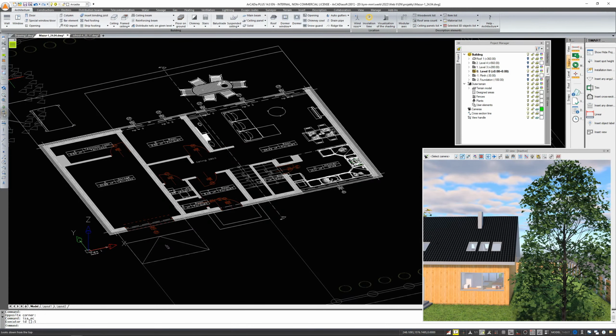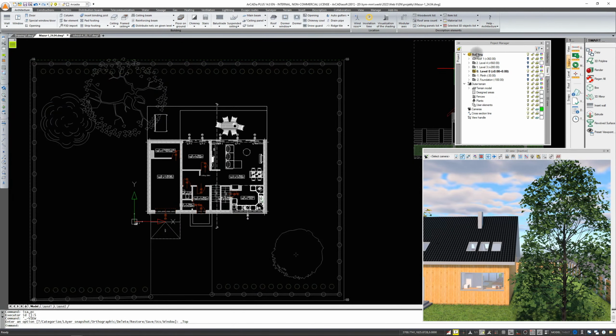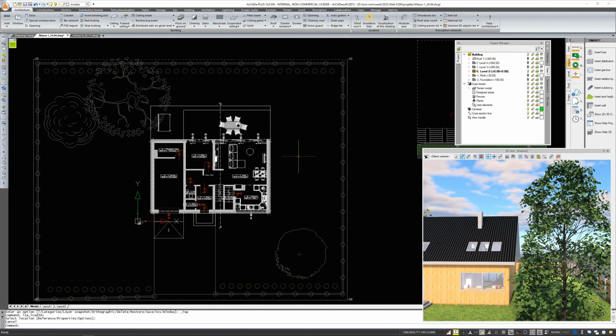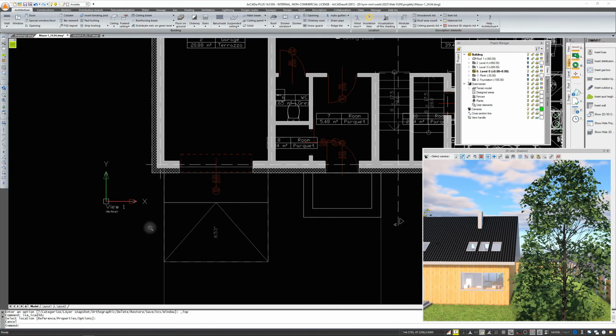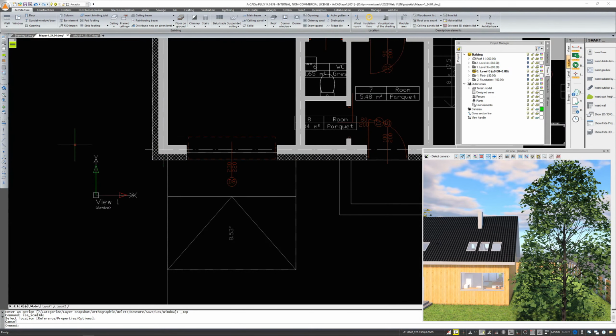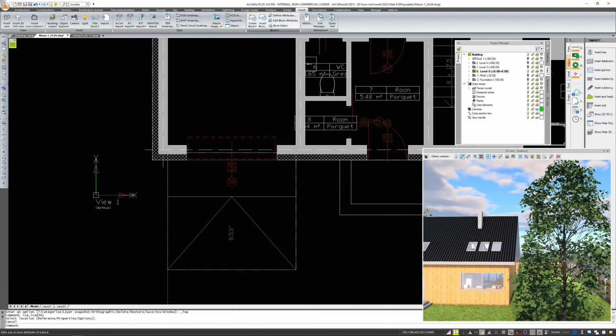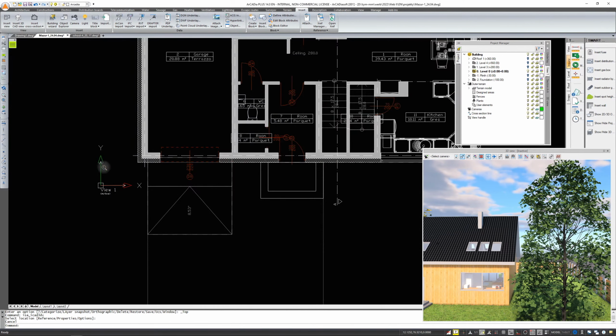When it comes to slightly lower spec and older computers, or those that do not have too much memory, I would even suggest that you insert the 3D view when you need it, and do not work on it from the very beginning. So how do you insert views? It depends a bit on the view. The view from the projection view, as you have seen, can be inserted just through the view handle, which is here on the left. As for the cross-section, I have already showed you how that works.